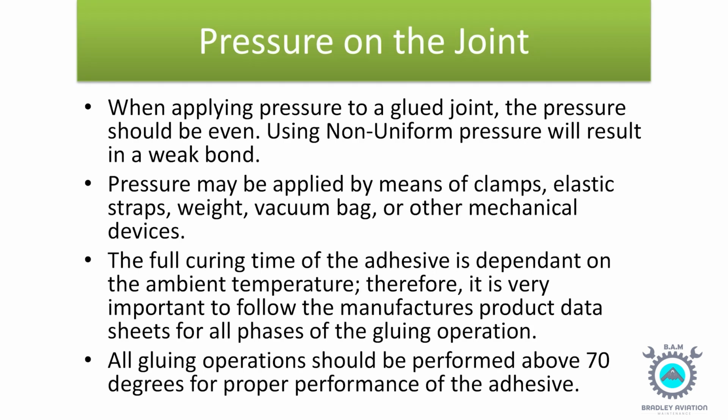Pressure on the joint. When applying pressure to a glued joint, the pressure should be even. Using non-uniform pressure will result in a weak bond. Pressure may be applied by means of clamps, elastic straps, weight, backing bag, or other mechanical devices. The full curing time of the adhesive is dependent on the ambient temperature. Therefore, it is very important to follow the manufacturer's product data sheets for all phases of the gluing operation. All gluing operations should be performed above 70 degrees for proper performance of the adhesive.